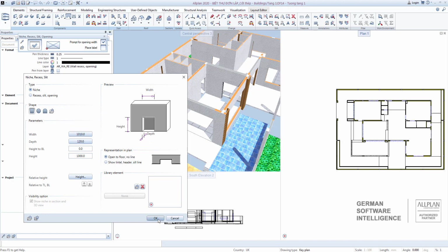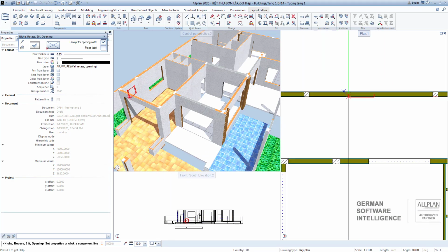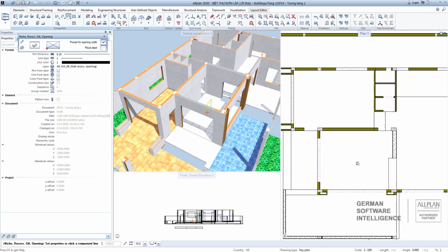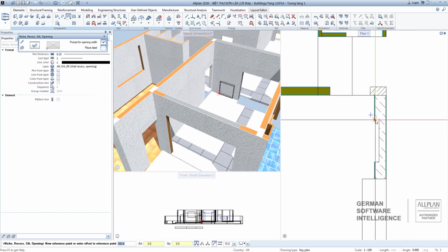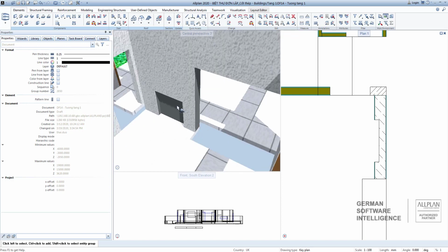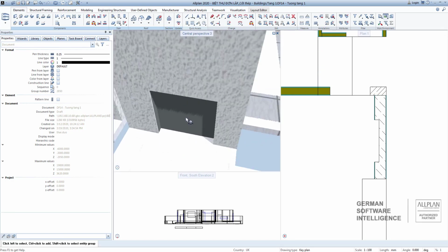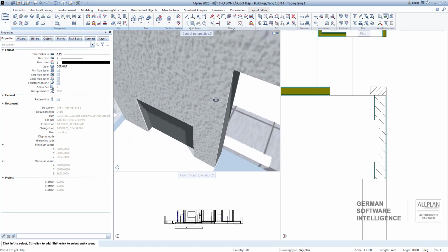When you're finished with the settings of dimensions, choose OK, then select the wall. Enter the location points and confirm the opening creation on the wall. So, as you can see, we made an opening in the wall like this. You also often encounter many such cases.